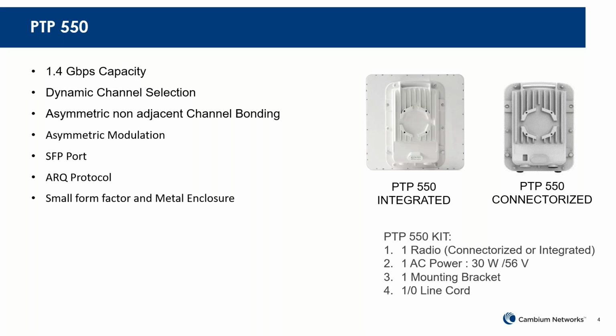And we understand it's an unlicensed band, so we implement the ARQ protocol, so the data can be retransmitted. Later, when we share the use cases, you can see that in areas where there is a lot of interference, ARQ really makes the difference.